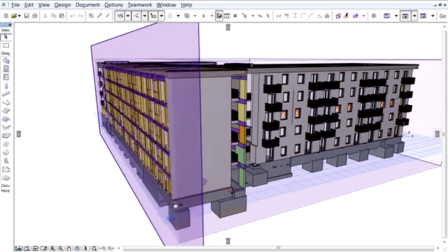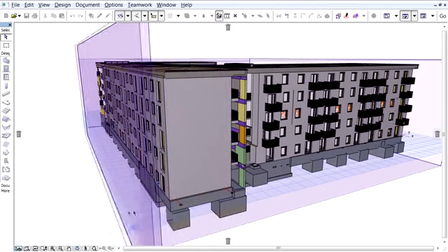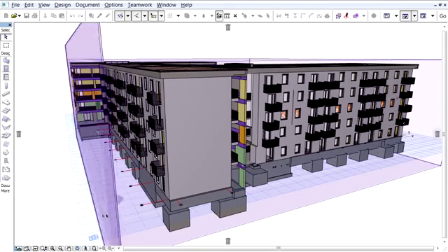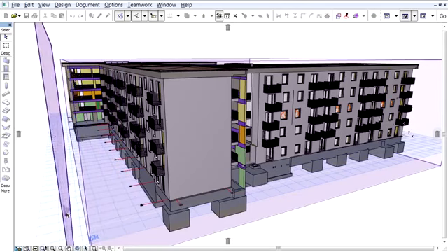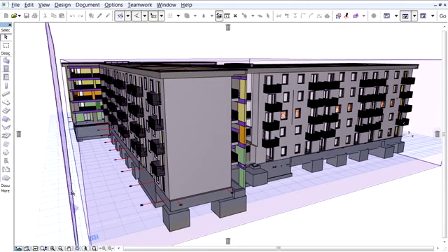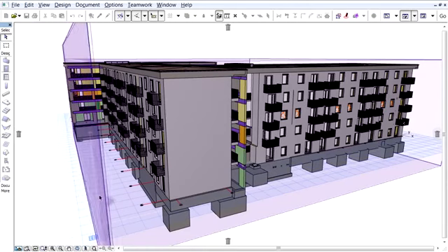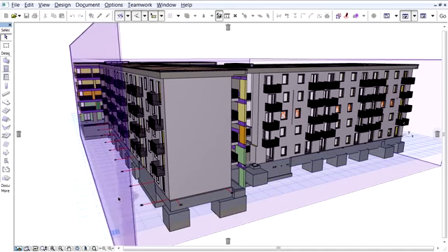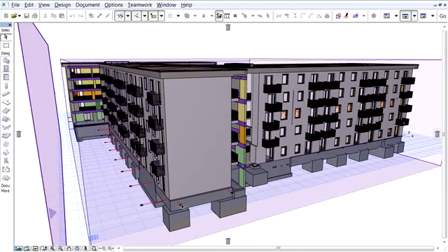In certain cases, it might be hard to move the cut plane and snap to the edges or nodes at the same time. ArchiCAD provides help to ease the positioning of 3D cut planes. Let's start dragging the cut plane and then press the Shift key on the keyboard. This will temporarily move and fix the 3D cut plane next to the building model.